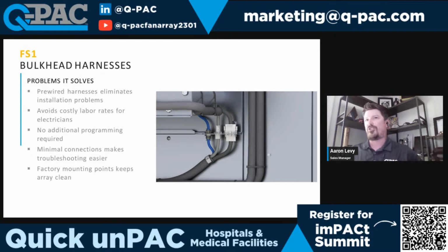So new electronics would have to be developed, and for such a limited market, normally we use step down transformers, and that normally is enough to get us through these particular applications. Even with OEMs, when we were selling EC fans into the OEM market for the Canadian market, they would often step down 575 to 460 or 480 and do it that way, and that seemed to be sufficient. I just don't see it on the horizon. I'm sure each manufacturer has that in their playbook as a roadmap item. I just don't know if it's a hot button issue that will happen in the next couple of years.